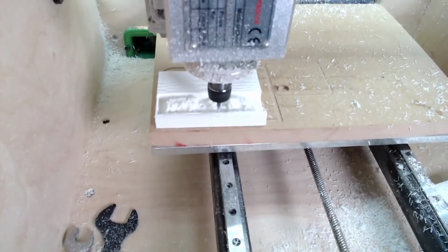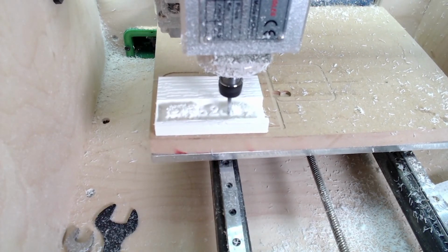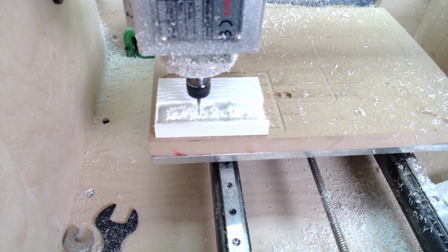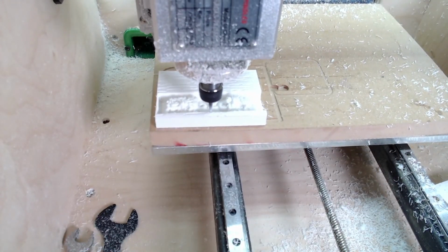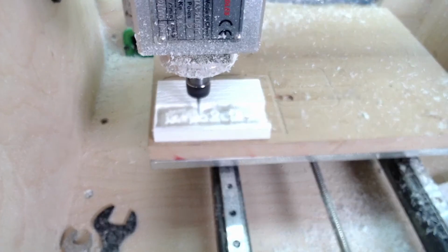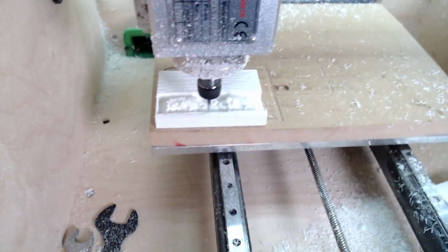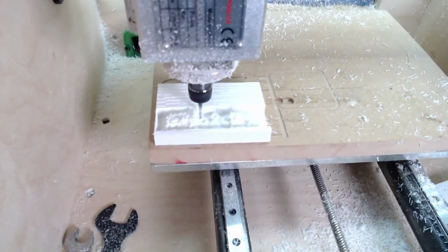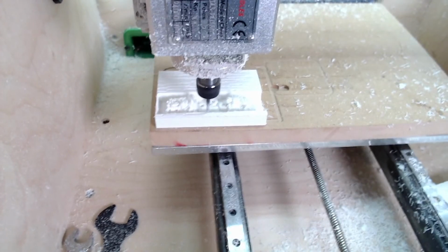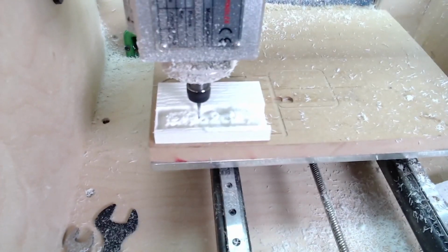So I'm not changing the steppers out. They sent me some encoder boards that basically you glue magnets onto the back shaft and hook up these encoder boards, and you can close loop existing steppers. I was hesitant to change out my steppers since I had just tracked down linear motors for this machine.